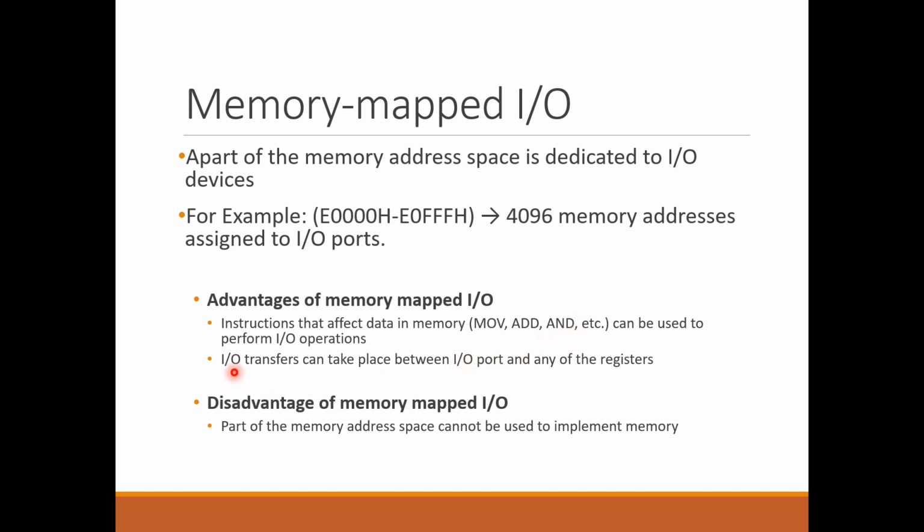Even the I/O transfer can take place between the input output devices and all the other registers, while in the isolated I/O only AL and AX could be used, but here any other register inside the 8086 microprocessor can be used in order to transfer data.